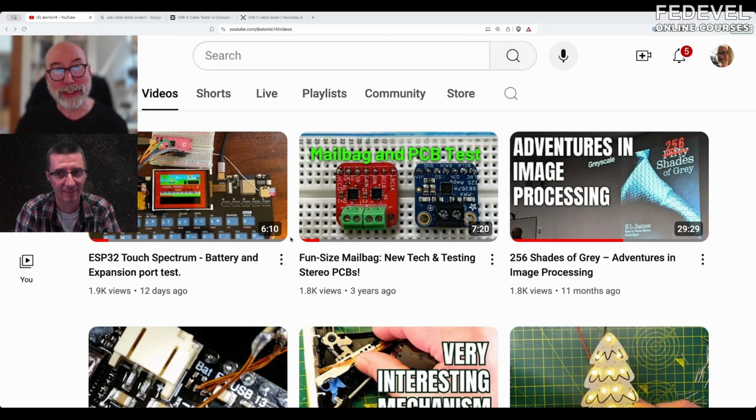And I was looking, I thought, oh yeah, you could. I was reading all the docs on the ESP32 GitHub about how to use matrix touch pins. I thought, yeah, this could work. And I looked at how many touch pins the ESP32 had, and it didn't have enough. And I was just, oh, I can't do this project. And then I looked at the ESP32 S3, and they added more touch pins. And I thought, I can do this now.